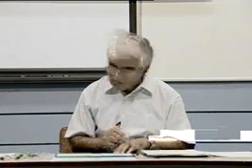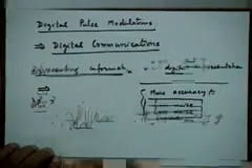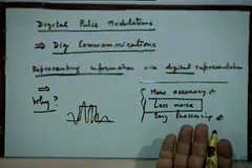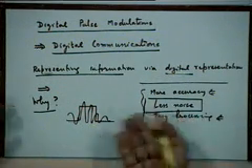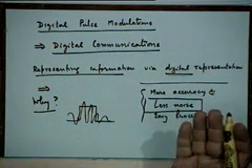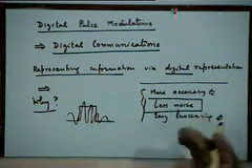But the digital signal can be easily recovered. Now, let us see. Here is a digital pulse, right? And you have added this noise. At the receiver, what will happen? By itself, it does not do anything. In one sense, if we have some analog signal and by some small noise its amplitude gets very large, that variation will not be very much seen in this digital case.